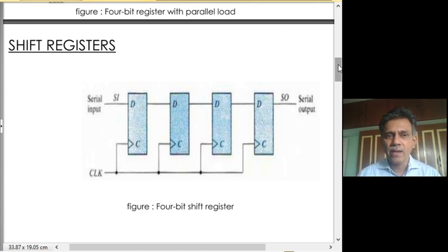Here we take only 1 bit at a time and store it at an appropriate place, and then take the other bit and store it. Similarly, when you're reading it, you will read only 1 bit at a time. So if you have a 4-bit binary number, you store 1 bit at a time, using 4 clock periods to store those 4 bits in successive clocks.